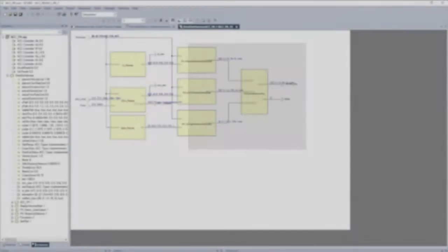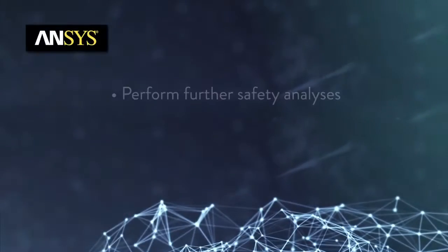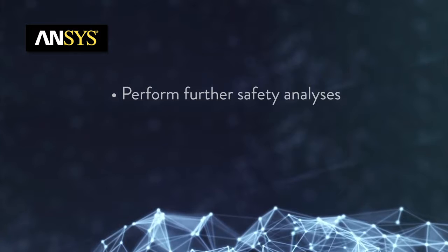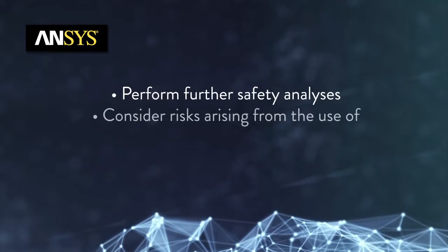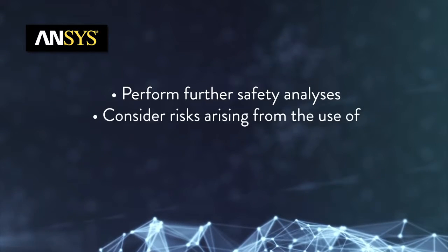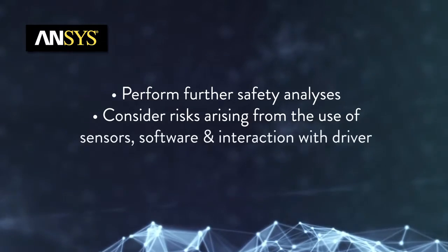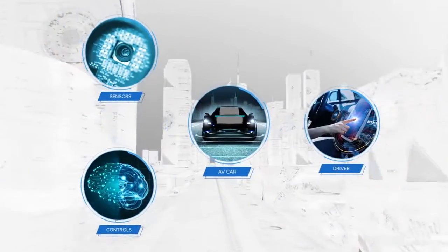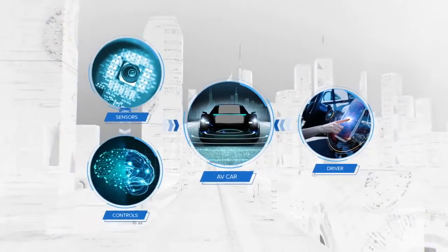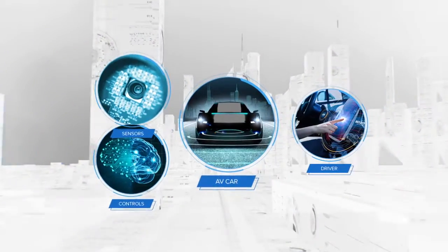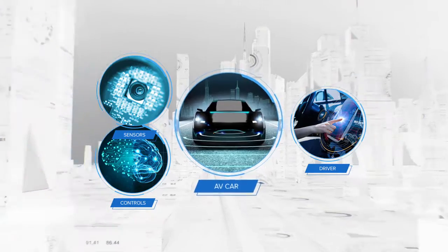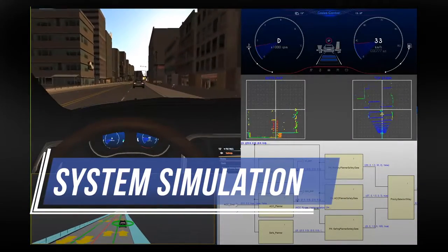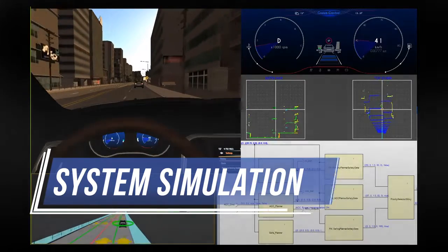We can now perform further safety analyses following the SOTIF standard, which expands on ISO 26262 and considers risks arising from the combination of sensors, software, and the interaction of those with the driver. For example, SOTIF analyses considers whether the system will work in varying weather conditions. This requires simulation. We now test the system with a closed-loop simulation in a virtual environment.